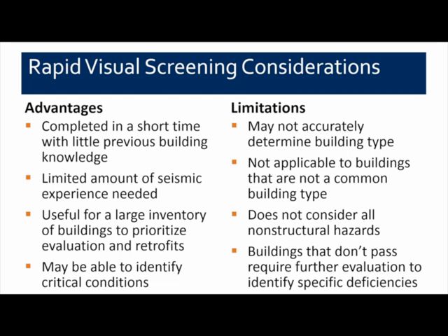But some of the limitations in trying to use this procedure is you may not actually be able to determine what the building type is because you're only looking at it for such a short time. And as Kelly described, a lot of the structural elements may be covered by finishes. So to accurately define the building type is sometimes very difficult. And this is also not applicable if you're looking at a building that doesn't fall into one of the common building types that Kelly described.